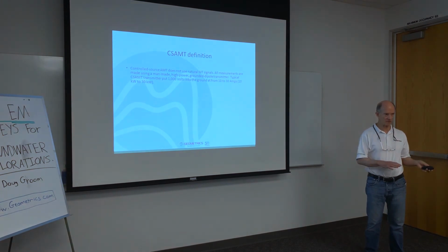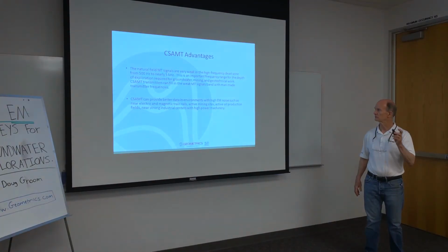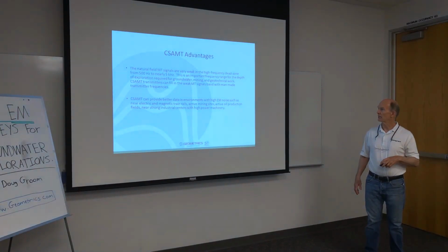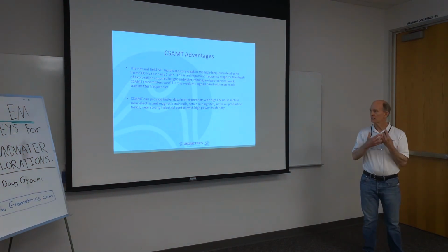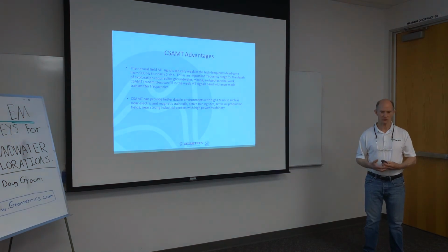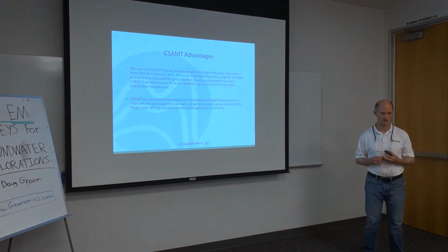CSAMT is a very different technique that only uses a controlled source transmitter. As a matter of fact, the natural sources are a noise source in this technique. They're not used. When would you use CSAMT? Typically, it's only used when there is a very strong cultural noise environment that you must deal with on that particular survey site.